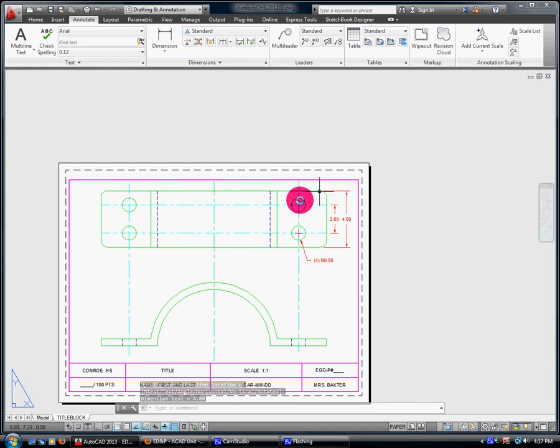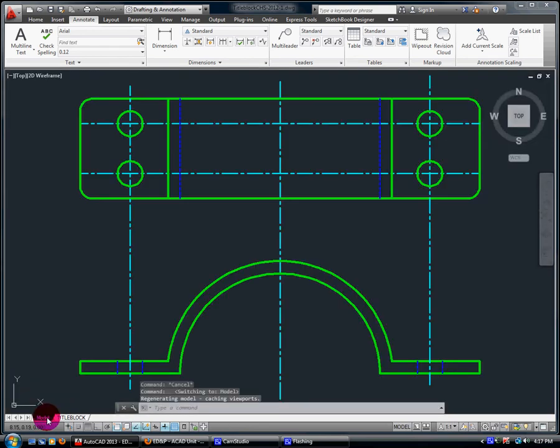What I want you to look at, this looks like it should. Notice how the font and the arrows match the same size down here. So when we print them out, they're that 1.25. I want you to see what happens if I do the exact same measurement here, but I do it in model space. I want you to see how small they are.